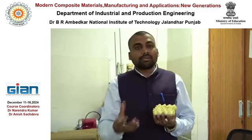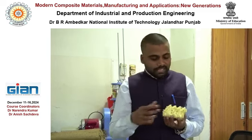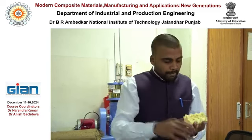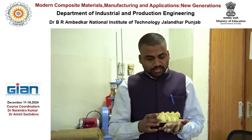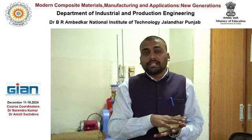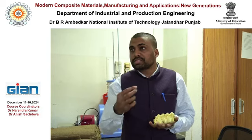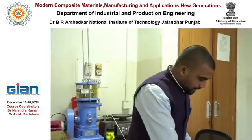How strong your matrix and reinforcement interface is decides how efficiently your matrix will transfer the load to the reinforcement. And if there is any void, so void is again a defect, that particular void will become a stress concentration point, and from there your composite will start to fail or deform, right?